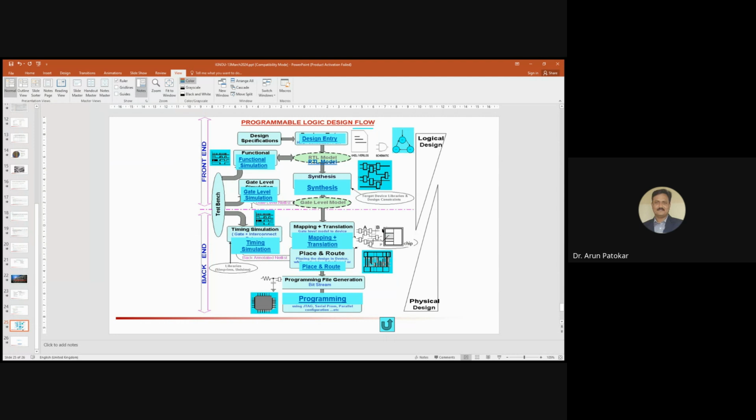into the hardware form, and then choose the program generation, the bit file generate, and with the help of JTAG serial communication or parallel communication you can impose that design and take an embedded device ready with the field programmable gate array or CPLD devices.